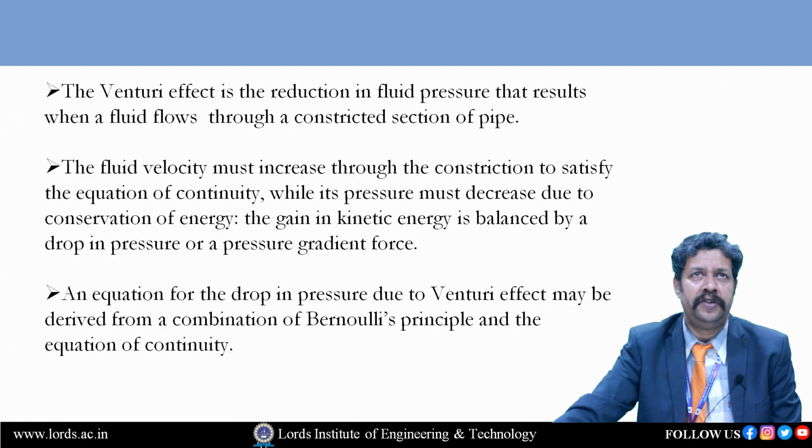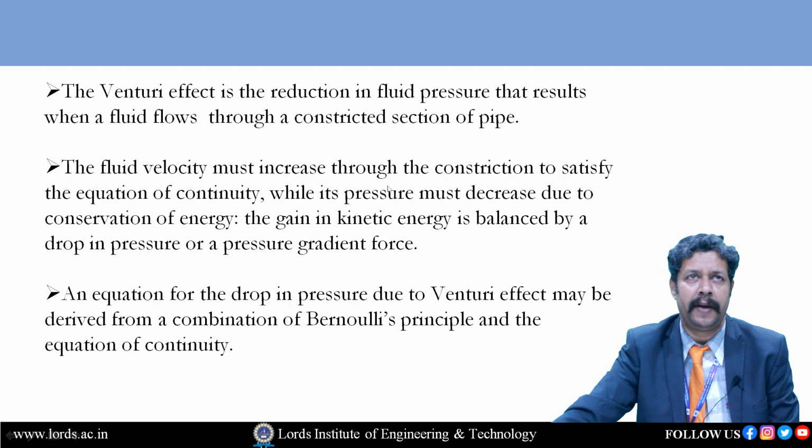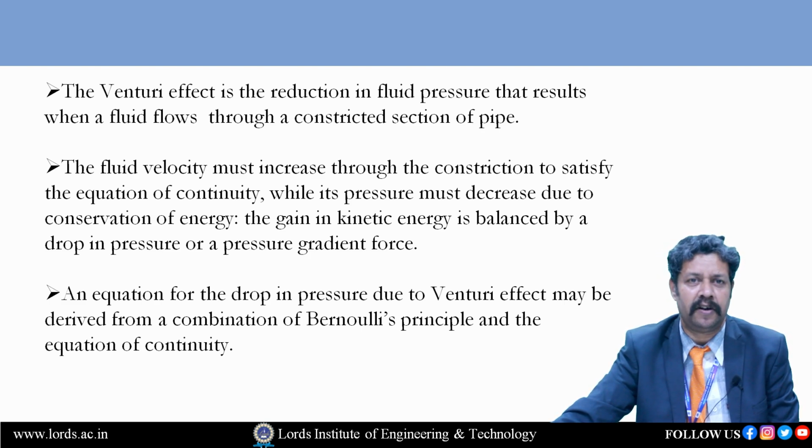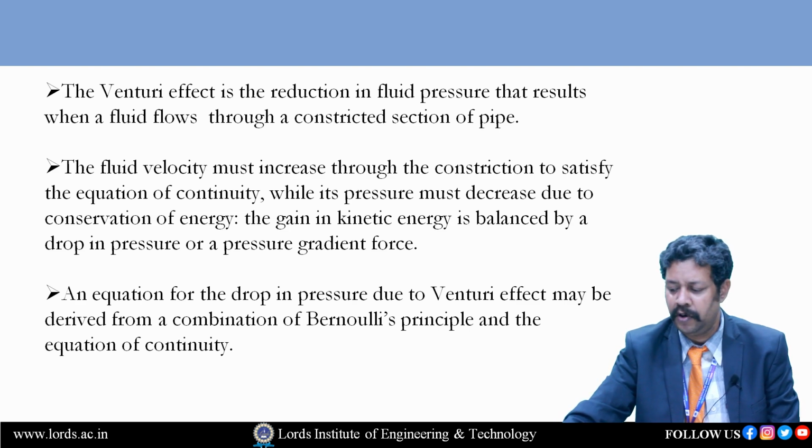Next, the Venturi effect. Mainly, we are considering a particular pipe where the velocity is increasing, where kinetic head is increasing, where pressure head is decreasing. So all these things we have to study. It mainly depends upon Bernoulli's equation as well as the continuity equation. Continuity equation is nothing but discharge is constant. Q at two different sections: A1 V1 is equal to A2 V2.